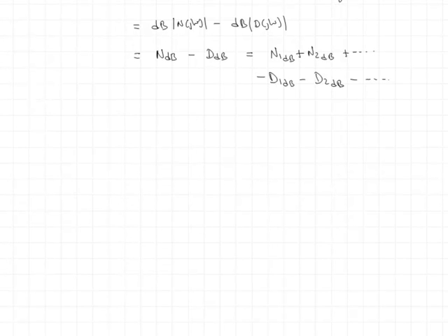Now let's look at phase. All right. In other words, I'm going to claim again that determining the phase of the overall transfer function g of j omega is readily done by simply combining the phases of each of the numerator and denominator terms.